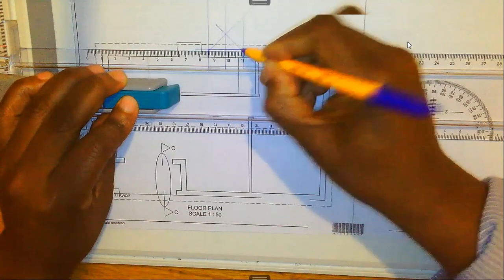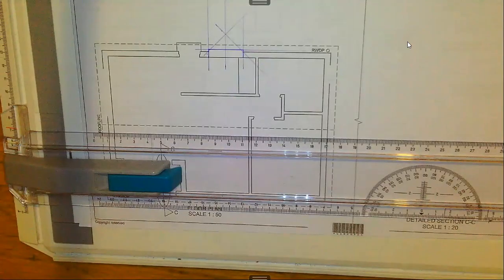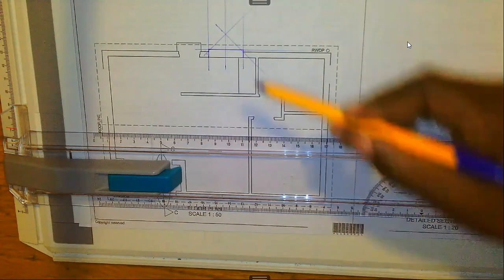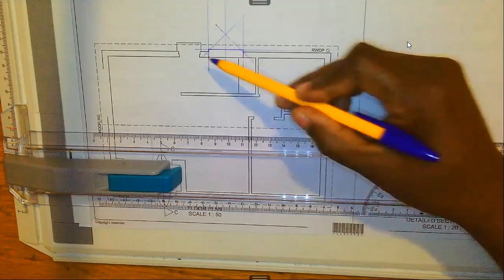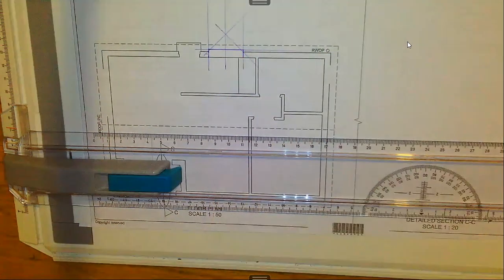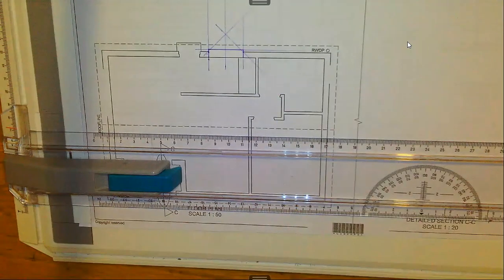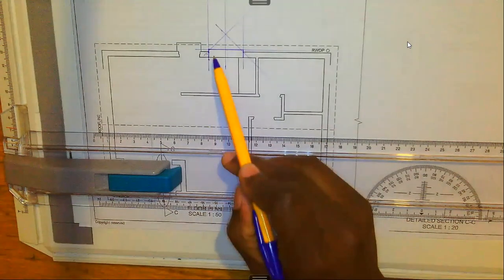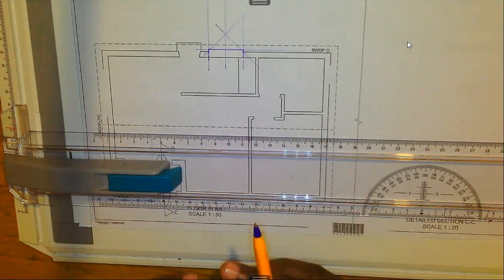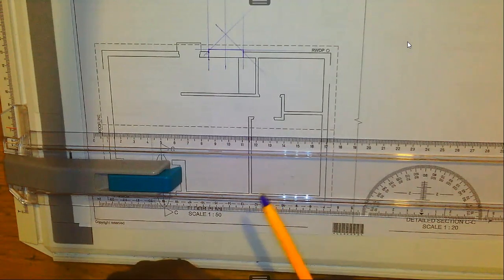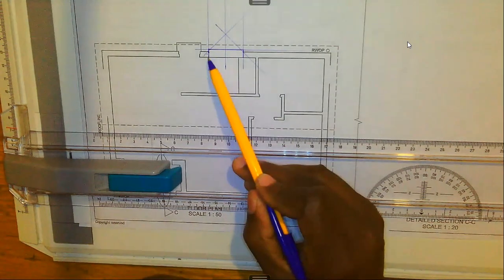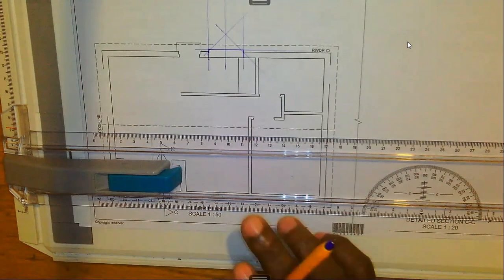Sometimes you may not need to completely outline, make it slightly thicker than a construction line, but not as thick as an outline, especially the extension from here to there, and this outside one. But because this part defines the wall, you need to outline that part. Right, once you have done this, you now need to position the frame, which means the window frame, right? Remember, the window frame is positioned right in the middle of the wall.